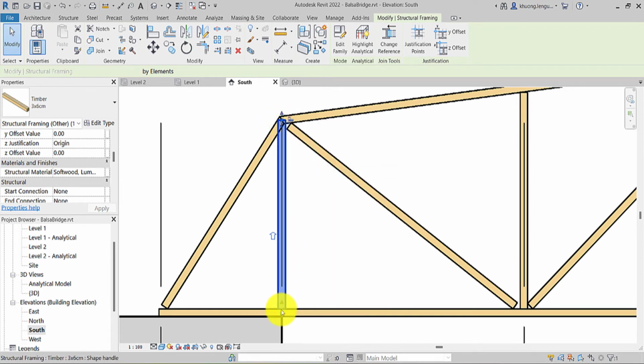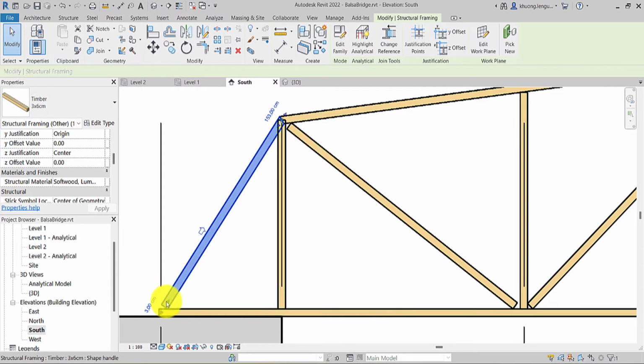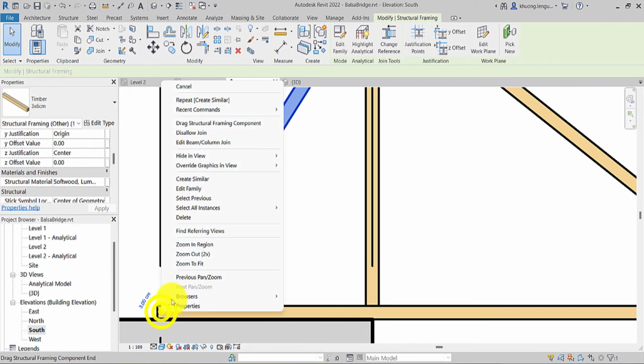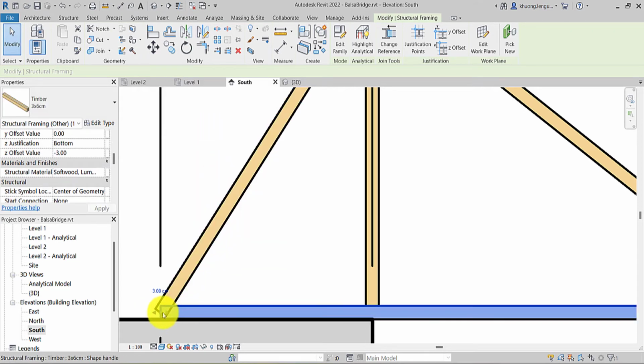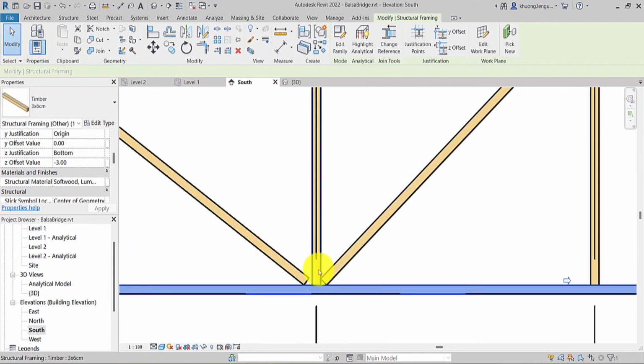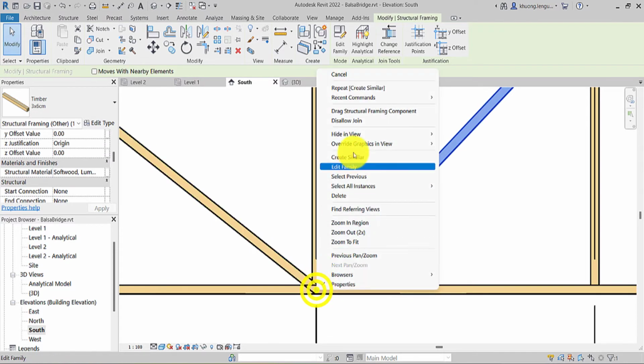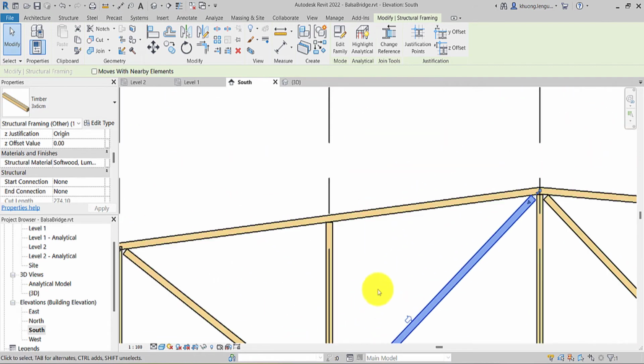We will notch the bar in this area. So to do that, we need to extend the X bar, and let's do it, and you can understand why. To extend the beam element to their joint point, you select the point, right-click and choose the Disallow Join option.